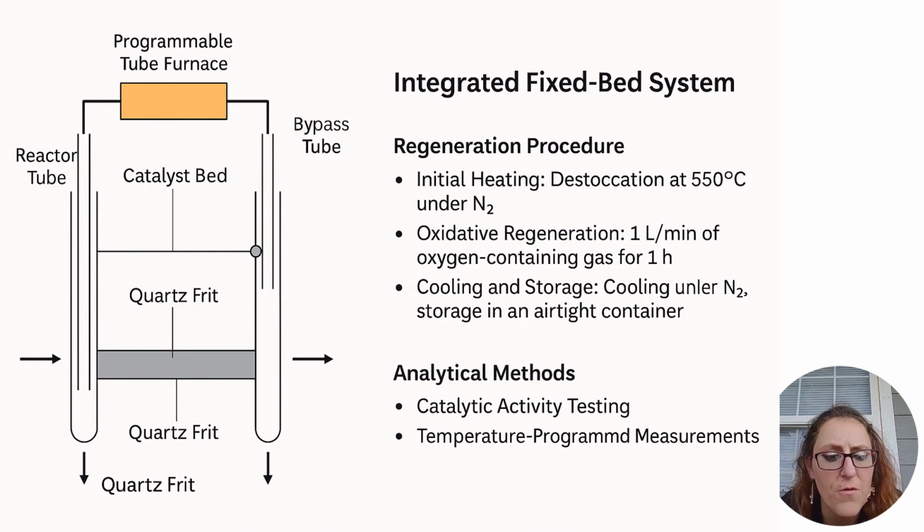And temperature-programmed measurements: temperature-programmed oxidation and reduction analyses were performed to characterize the redox behavior, phase stability, and oxygen mobility of the regenerated catalysts. The resulting profiles revealed the ease of vanadium redox transition, which correlates strongly with catalytic performance. This integrated fixed-bed system provided a robust platform for studying the relationship between regeneration atmosphere and catalyst reactivation.